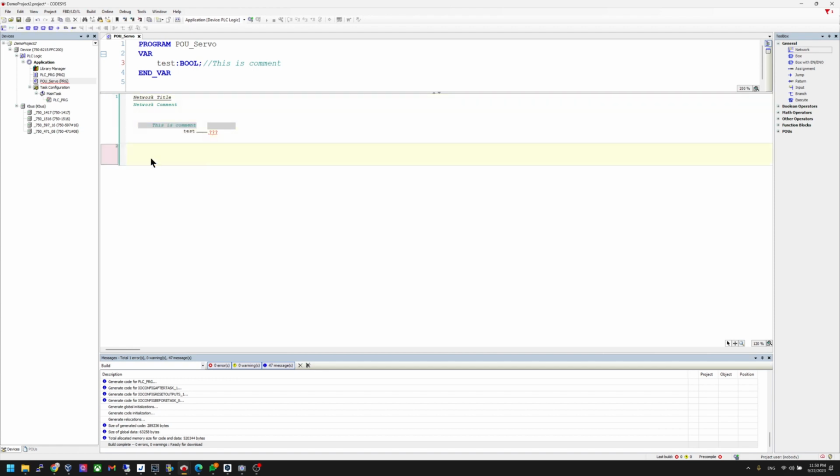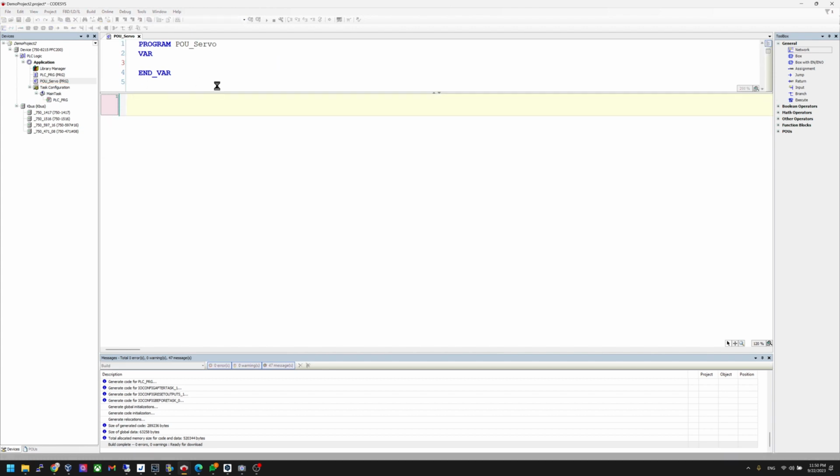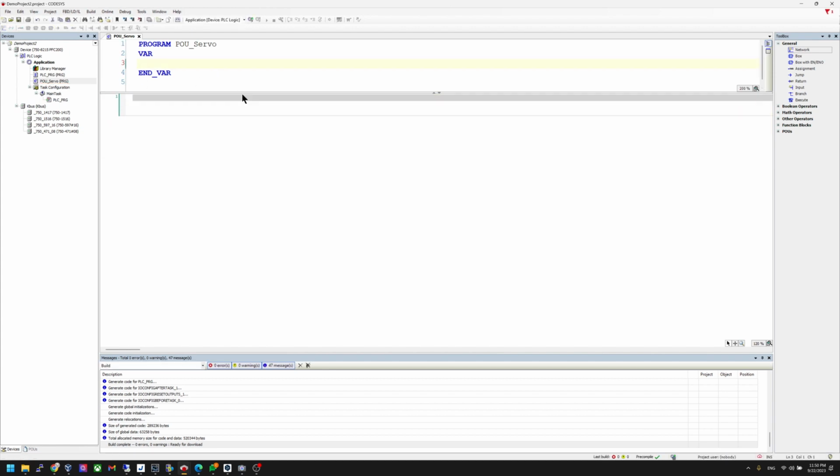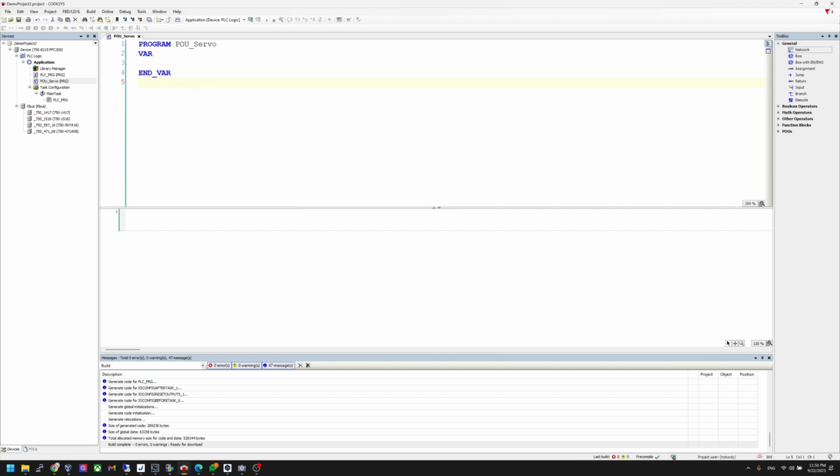So now we need to delete all the parameters that I don't use here, and I'll start the programming. Before I program it, I will define some variables that we'll use in this program. The first one, I would like to define two slots of byte type. That is for me to map the data between my user program and the real hardware. In this case, it's WAGO's digital input and digital output.